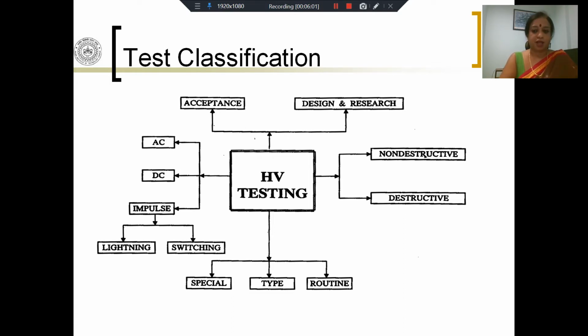would destroy it. So therefore, we have to have some non-destructive tests, and non-destructive tests are generally geared at trying to estimate the change in properties, dielectric properties of your material, such that you can foretell or predict the life or the viability, the functionality of the system. We will talk about destructive and non-destructive tests later.